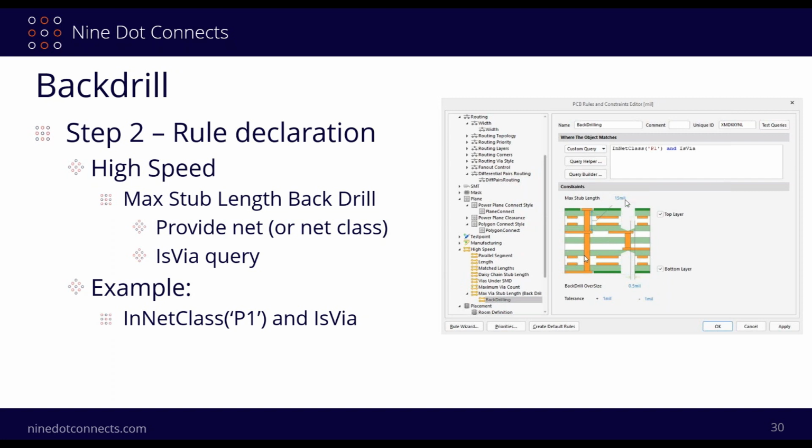And then, how much is the max stub length I'm willing to allow? You're never going to be perfect, right? Even though I want everything below layer 5 to be removed, and of course, in theory, I'd love to be right up to layer 5, so there's absolutely no stub, let's be realistic over here. We've got a drill that's going through this, and there are tolerances that we've got to deal with. As a result, leaving a little bit of a stub length is going to be okay. I think 15 mils is a little much, but nevertheless, I think that's the default here in this example. I take that back. I think it may be 5 mils. I may change that to 5. I was probably doing this to exaggerate some of the pictures, so I'm not going to blame this one on Altium. That's just probably my doing and taking a picture of it thereafter.